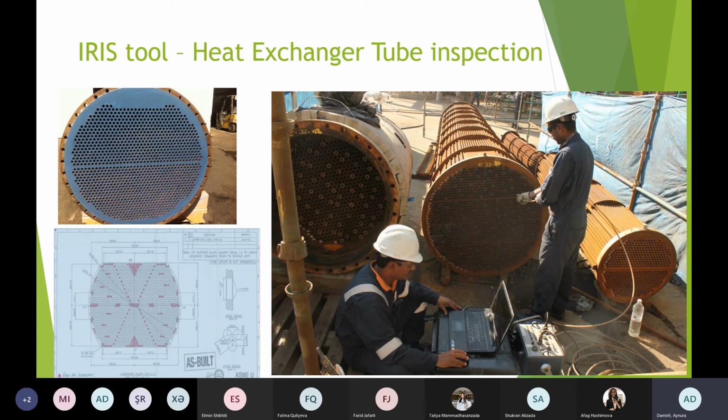So from an inspection program point of view, you can see this process in the picture. As an example, this is a heat exchanger in one of our facilities, which has 2080 tubes. 2080 tubes must be inspected to see integrity, but we are inspecting only 10% of tubes, and this is not just random checking. These are the more susceptible areas inside this tube heat exchanger, and tubes have been selected based on industry standards like a tube inspection plan.